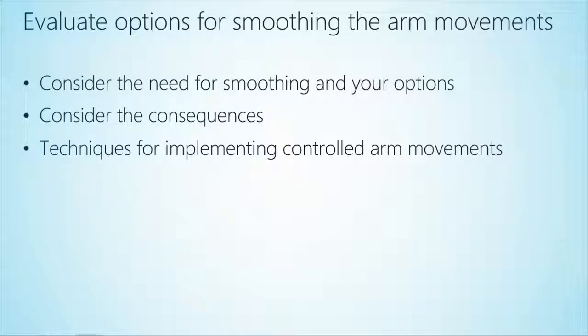It's just swinging back and forth. It's not moving something. So it's more important when you are going to be moving something, and that's what our demo is going to show, right? If you're moving something from side to side or you're carrying a heavy load, you don't want to just snap it to one spot because it's going to put a lot of stress on the servo motor to either stop or get started, trying to move quickly. So that's important. You always have to keep that in mind, and our little demo will kind of show that.